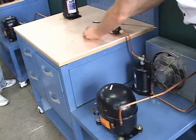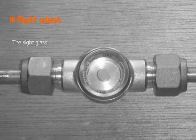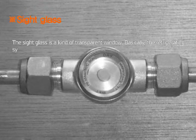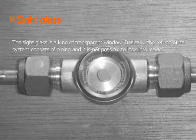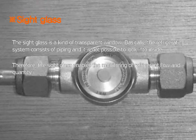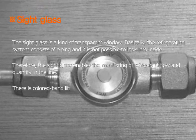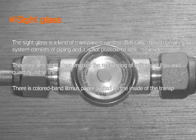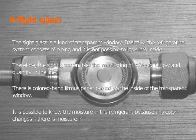Next, we connect the sight glass to the filter dryer. The sight glass is a kind of transparent window. Basically, the refrigerating system consists of piping, and it is not possible to look inside. Therefore, the sight glass enables the monitoring of refrigerant flow and quantity in the line. There is color-banded litmus paper pasted on the inside of the transparent window. It is possible to know the moisture in the refrigerant because this color changes if there is moisture in the refrigerant.